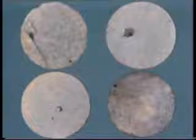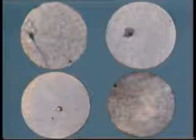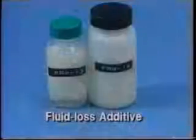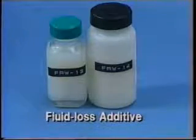Limiting the wormholes results in a more effective matrix acid treatment. Laboratory tests have shown that wormhole length is limited by fluid loss and not by acid reaction rate. Either a viscous emulsified acid or acid with a fluid loss material is effective.